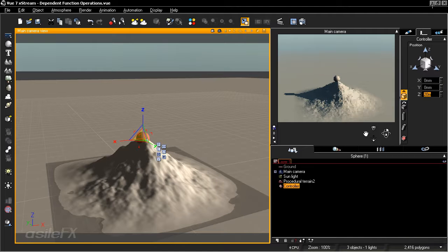Now we set the value to 20 meters on the Z. So right now at 20, the blender is set to 0. If we change it to 40 meters, it's going to set the blender output to 1. So now we are seeing the noise node and not the fractal. If we set this to 30, we're going to see a value of 0.5 and halfway between the blender, between these two nodes. So it's a control for our range slider of the blender output ratio between 0 and 1, which is represented by 20 at 0 and 40 at 1, because we set our range to 20.